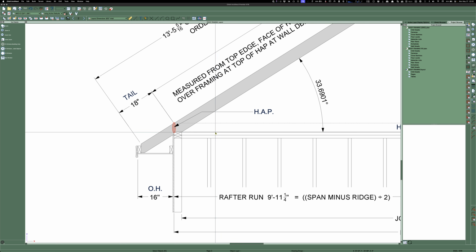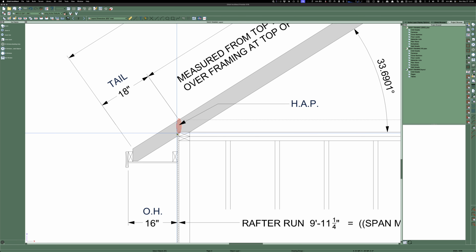Some people say, well, it makes it stronger in between. This is a 14.5 inch span. And if you're going to put something right there in the middle, first of all, you need a stack frame, which means joists and rafters. You pick one. I usually like my rafters to go right above where the studs are, and the joists can go on either side, as long as they're on the same side equally through. But this is nuts.